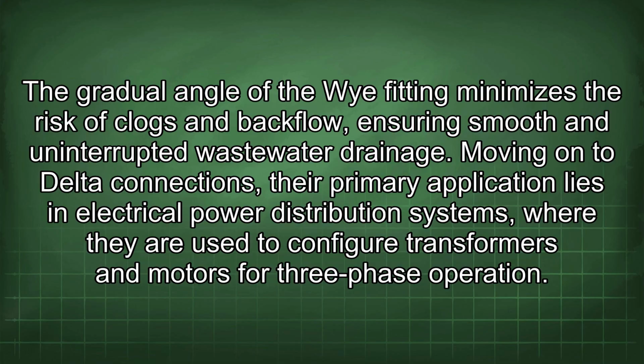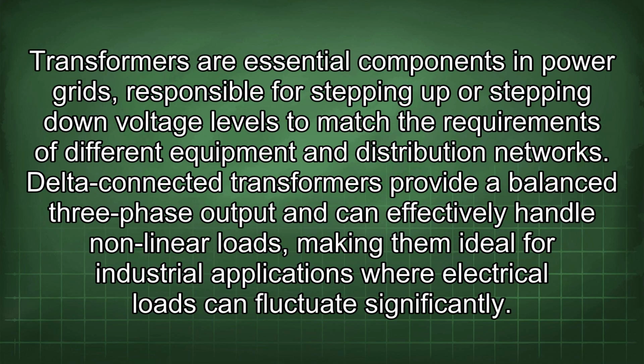Moving on to delta connections, their primary application lies in electrical power distribution systems, where they are used to configure transformers and motors for three-phase operation. Transformers are essential components in power grids responsible for stepping up or stepping down voltage levels to match the requirements of different equipment and distribution networks. Delta-connected transformers provide a balanced three-phase output and can effectively handle nonlinear loads, making them ideal for industrial applications where electrical loads can fluctuate significantly.